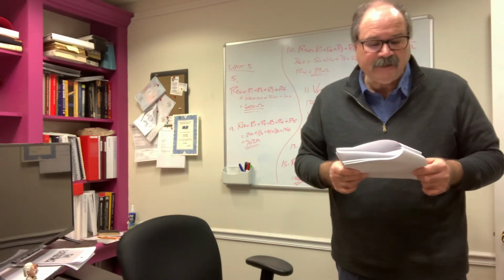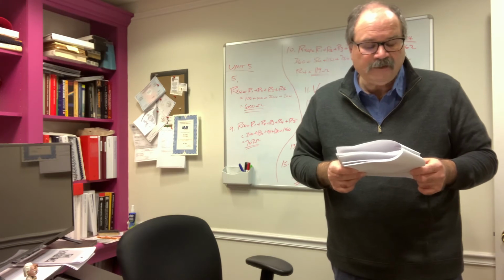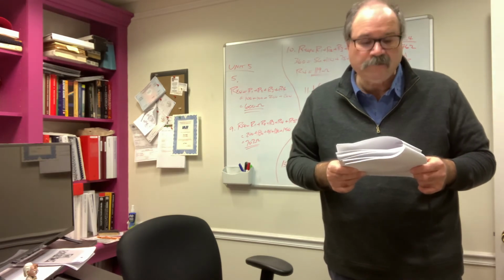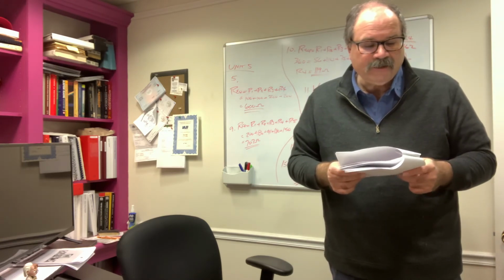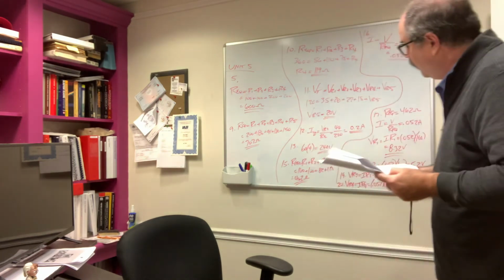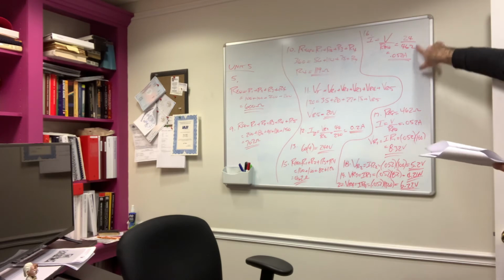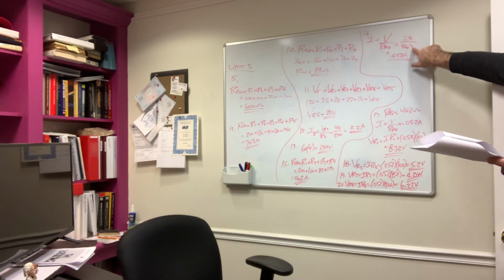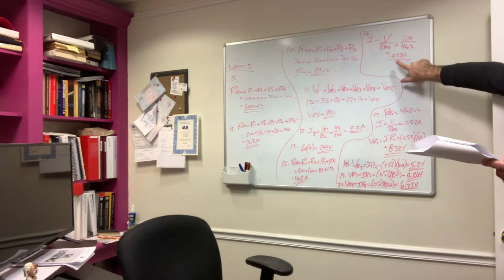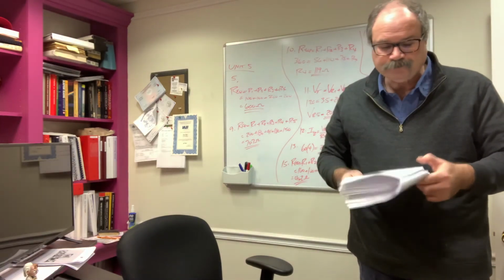Question 16. A series circuit is constructed from 4 resistors with values 160, 100, 82, and 120 ohms respectively. It's connected to a 24 volt power supply. What is the total current of this circuit? So in this example, all we have to do is take the voltage given as 24 volts divided by the equivalent resistance, where we add up 160 plus 100 plus 82 plus 120 gives us 462 ohms. Plug these numbers in, we get a current value of 0.052 amperes.